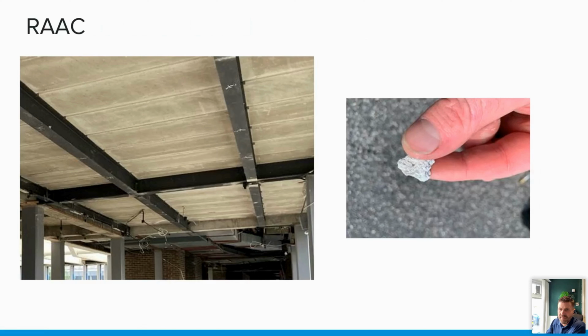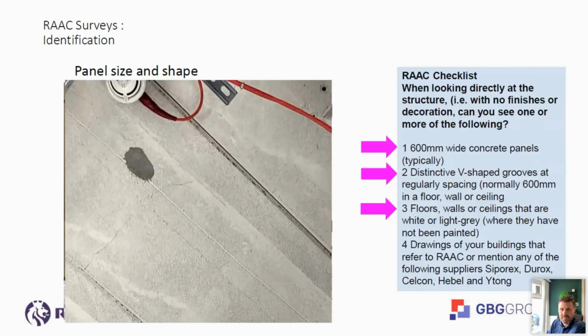The thing with RAAC is, if it's suspected, my advice as a surveyor is that an assessment needs to be carried out by either a structural or chartered civil engineer, and they have to be familiar with the assessment of reinforced concrete structures. The government did put out an advice paper on it, so have a read of that. Like I say, it was heavily covered in the news, so it's not worth me going on about it. This is a RAAC checklist that was put out by RICS. RICS have put more guidance out on this since I put this presentation together.